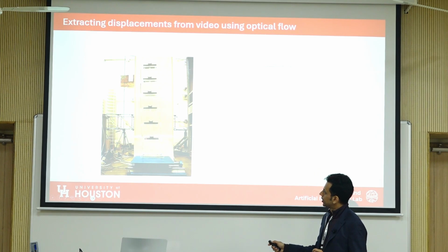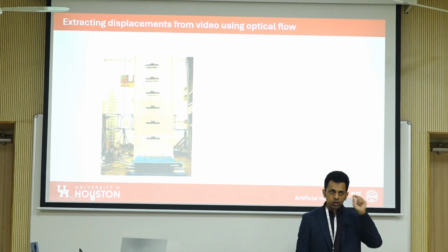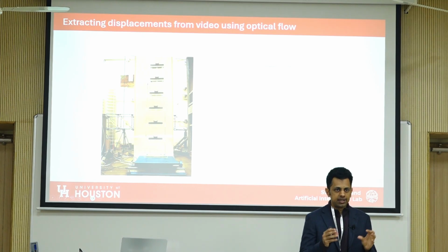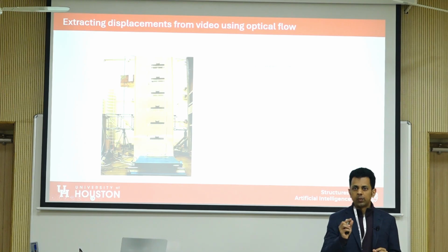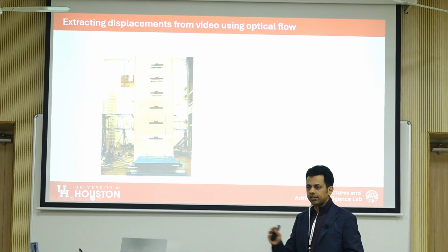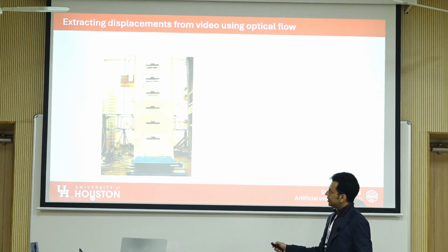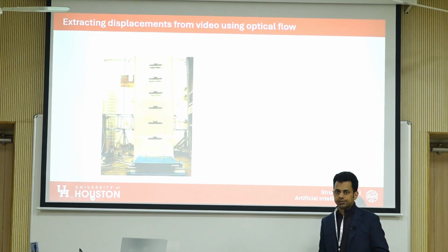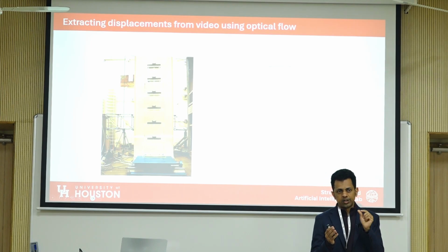Compared to the background, there's this rigid body that has the same intensity that's moving. So if we track pixels of constant intensity within the region of interest from frame to frame, we can find where this object is at any given point in time. If I get the pixel locations of each of these stories, I can treat each as a rigid body and average the locations for each story.